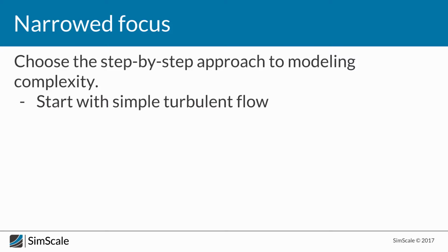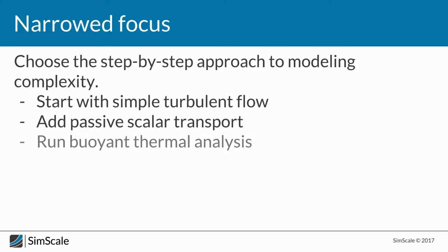This kind of analysis will also give us an insight into the way that air is moving within the domain. After that, we can start adding passive scalars. This is a minimal overhead over the standard simple flow, and will immediately provide us with information on how the air is changing, where the gases are located, and how they are propagating throughout the domain.